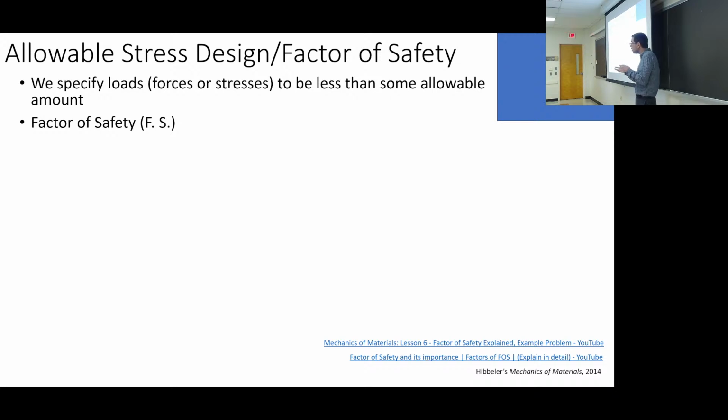In this class, it's very important, though, to be able to think about safety factors in terms of stresses. So I could have a force or a torque loading a structure, and then I gotta pinpoint, use my X-ray vision to figure out where that stress is a maximum in the structure, and then compare that stress to the yield strength of the material, or to the shear strength of the material.